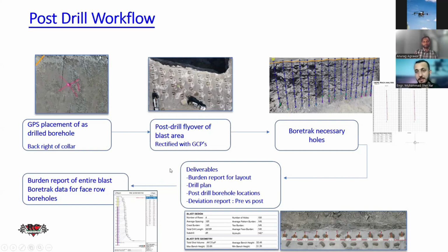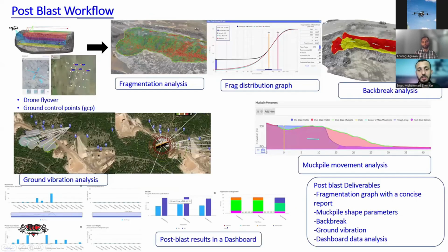of when the drill happened, when the blast is done. So you can do the fragmentation analysis, and you can extract the gradation curve for all the parameters like D10, D50, and D80. I think some of our attendees are familiar with this term, should be from mining site. So this gradation curve you can generate, and you can also